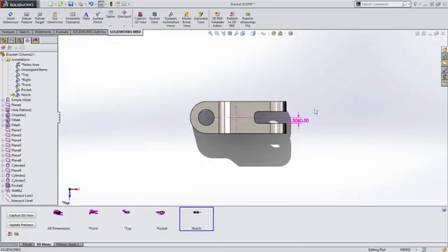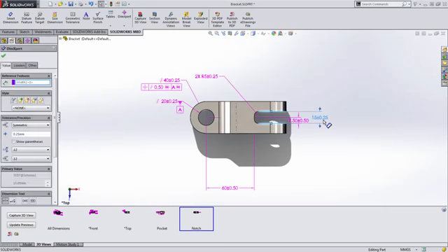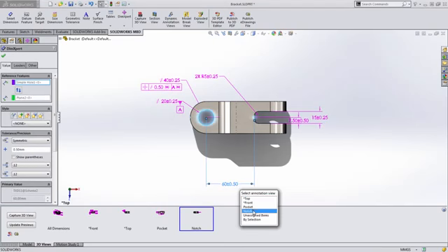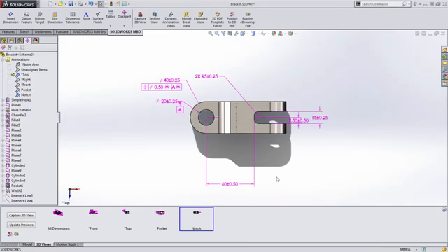Again, it looks like a case where some of the information isn't in the appropriate view. So what we're going to do is go ahead and turn some of those back on. Let's go to our top annotation view here, and we're going to redefine these to be part of the notch. So I'm going to select them and again use my hotkey to assign those to the appropriate view. Now when I double click on notch, you'll see that all the information needed is there.